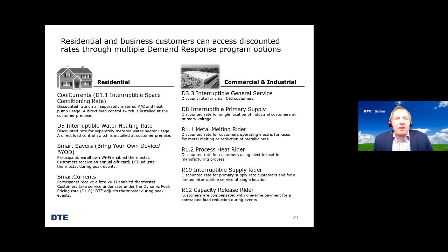Another popular program is the Smart Savers program, or Bring Your Own Device. In this program, customers who already have a programmable connected Wi-Fi enabled thermostat, such as a Nest or an Ecobee, installed in their home can enroll the thermostat in this program. The company will send customers a gift card at the end of every cooling season for their enrollment. During DR events, the company raises the set point on the thermostat anywhere from 2 to 4 degrees.